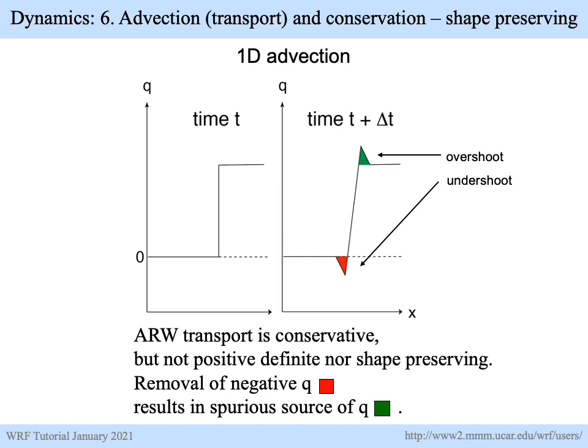You take a time step, and all of the schemes that I described, the second through the sixth order scheme, are going to produce, with a very sharp feature like this, typically overshoots and undershoots. You'll get both negative values, which are non-physical, and positive values, which are also non-physical, but harder to identify, where the solution is now greater than anything that existed before the step. So you see these overshoots and undershoots.